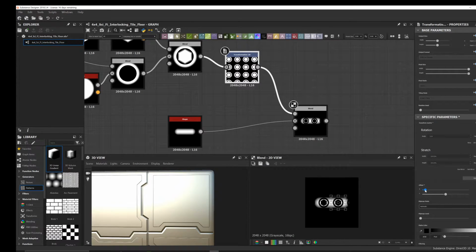And I only want 2 bolts in here. And we're not getting the right placement that I really want. So what I might do is just turn off tiling and place them both by hand. So I think this would be good at like -0.55.